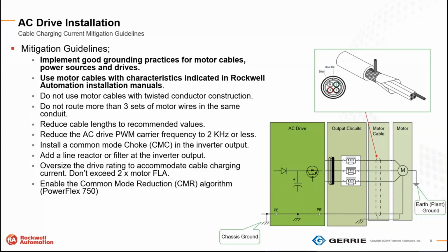Again, small horsepowers. Contractors running a bunch of motors out to a specific area, and oftentimes they'll run multi sets of motor leads in that conduit, then we get a lot of cross-talking going on there, a lot of cable capacitance coupling as well.